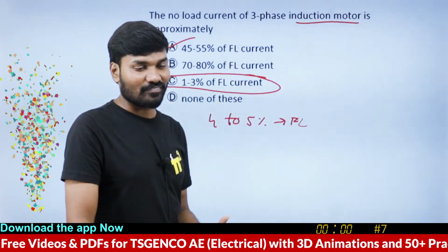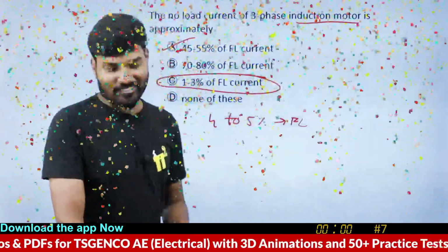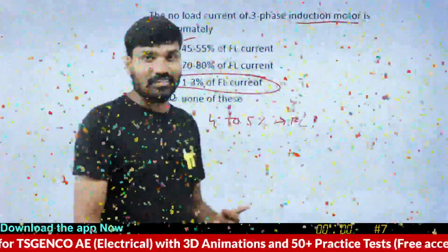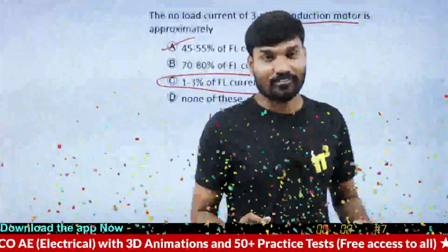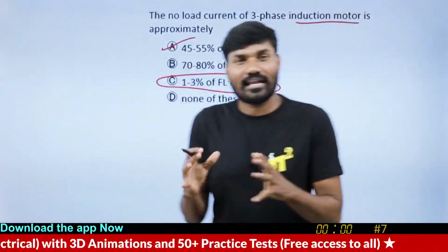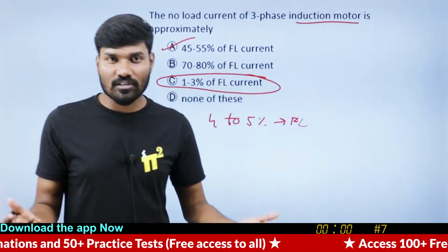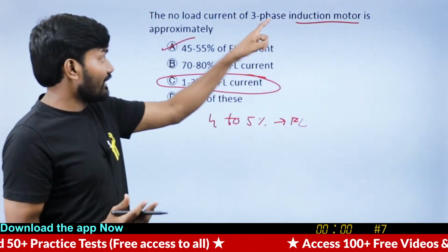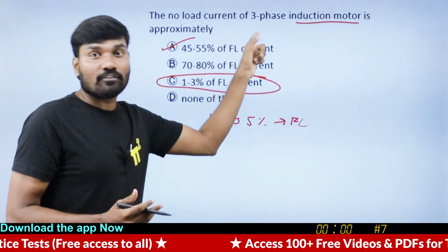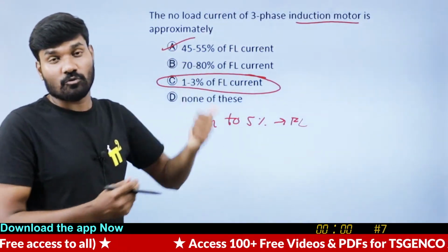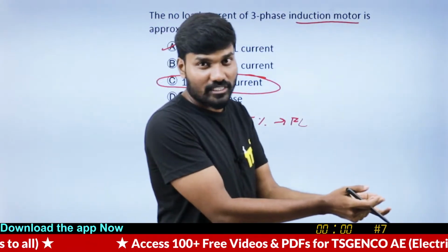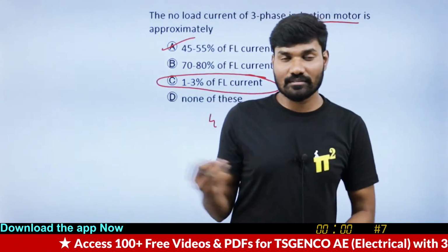Amazing, Raju. Rotational losses. In case of a transformer, there are no rotational losses. A transformer is static, mechanical losses are not there. No friction losses, no windage losses. But in case of an induction machine, they are there. That is also part of the no load loss. Somebody has to supply that no load loss, right? Who will supply? The input supply only will supply.